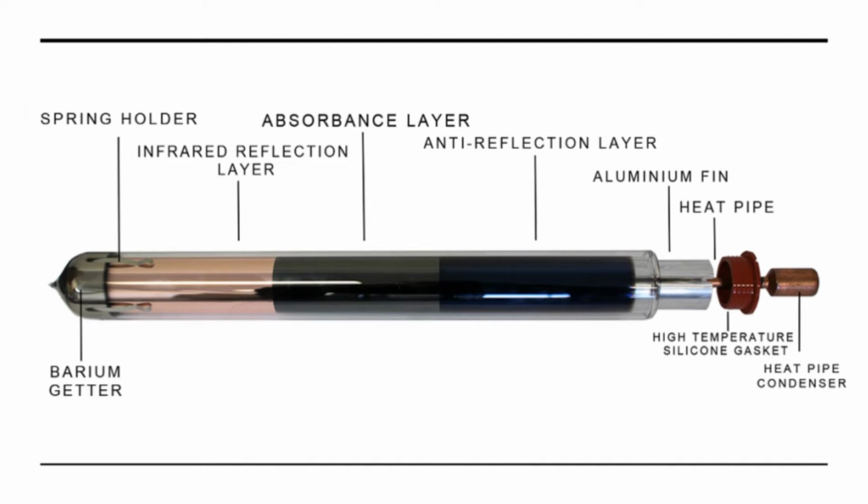The source of the heat comes from an evacuated solar heat tube, which warms up rapidly in sunlight. The evacuated tube collects heat to the aluminum nitride material, which is then transferred by an aluminum fin to the copper heat pipe at the top. The contents inside the tube are filled with an alcohol solution which vaporizes with increased temperature. The alcohol vapor then rises to the copper bulb, where it transfers its heat of vaporization, then condenses and moves back downward.